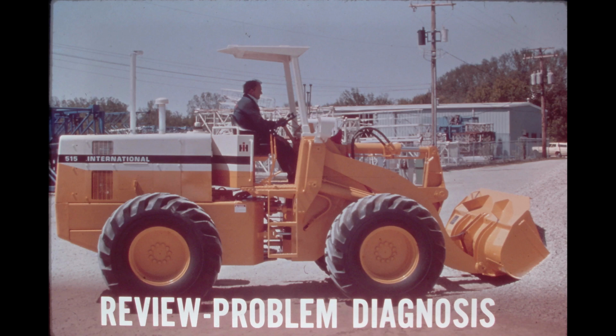The answer to number 1 is C. Transmission oil must be covering the lower sight glass before starting the engine. The answer for number 2 is B. A converter transmission problem is indicated if a good engine high idle reading is accompanied by a converter stall reading that is higher than specified.